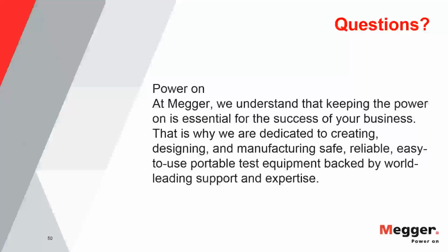And just to make this clear, this is not something that is new overall in terms of technology. DAC was the first diagnostics technology that was qualified internationally to give you 50, 60 hertz comparable results. And there's pretty much no discussion in the industry or no dispute that this is the case. Originally, this technology evolved for transmission type cables, from the high voltage cables, and is now migrated down into the medium voltage level. It is a very proven technology that is in use internationally for well over 10 years now. And IEC 60270 is the governing standard for that. All those waveforms are standardized and discussed in that standard as well.